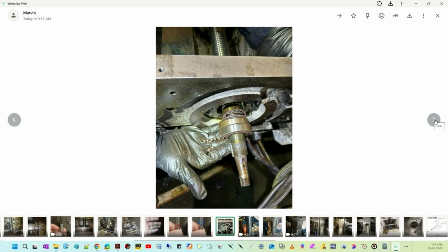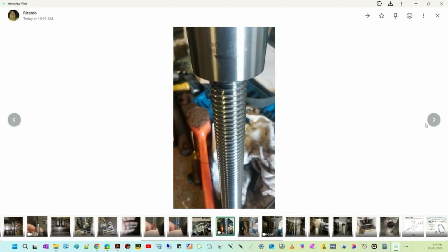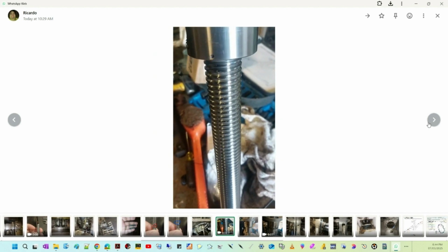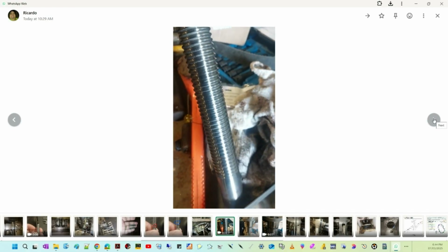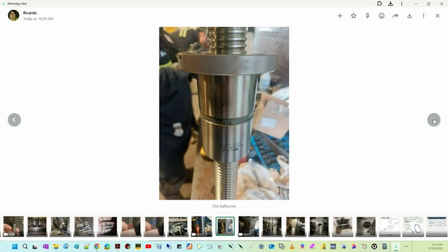It's a clear chain reaction. First, the cage failure happens. The cage breaks apart. This allows the ball bearings inside to bunch up, jam against each other, and against the races. Right, they're not spaced properly anymore. Exactly. This jamming causes the ball screw to seize, or at least become incredibly hard to turn. It can't rotate freely like it's supposed to, but the motor is still trying to turn it, following the commands from the control system. So the motor thinks it's moving, but the screw isn't really turning smoothly.